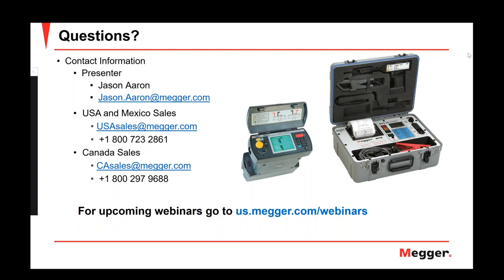So, as it was shown in the presentation, the method is injecting a current, or having a current circulating through the cell, and measuring a voltage drop, and that allows you to measure an impedance. So in that sense, you could say that you can apply this to all types of batteries. However, the important thing here is how to analyze the results.